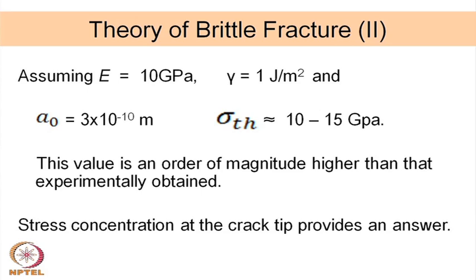Here also we find that this theoretical value is an order of magnitude higher than what we normally measure experimentally, and there must be an explanation for that. We are trying to look at the reason why the experimental value is much less than the theoretical value, and we will discuss much more about it, but just a statement here: stress concentration at the crack tip provides an answer.